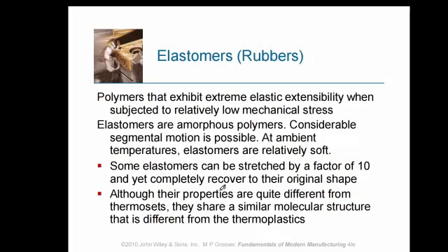And then elastomers, which are mainly rubbers, these ones are a bit different from the first two in that they exhibit extreme elasticity or extensibility when you subject them to mechanical stress. So they are very flexible, they can stretch and so forth. Another issue is elastomers are also amorphous polymers, meaning that they don't form crystals, they are not crystalline.